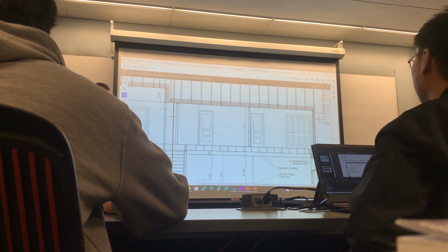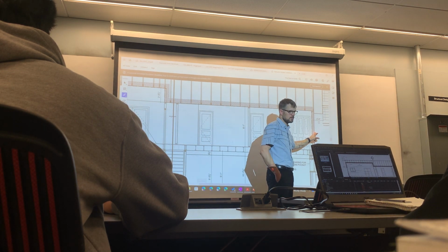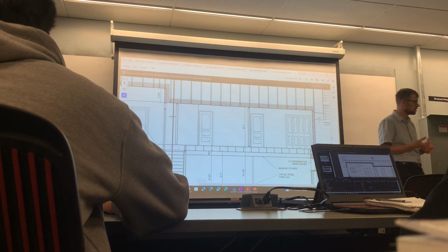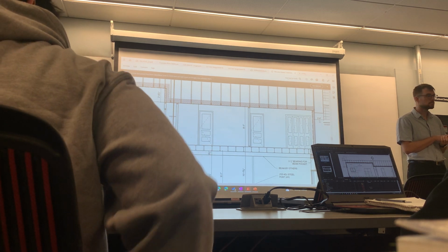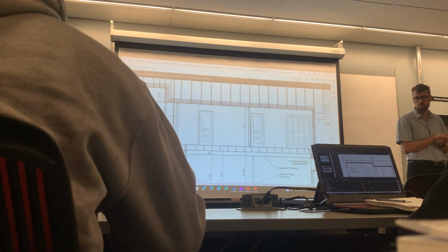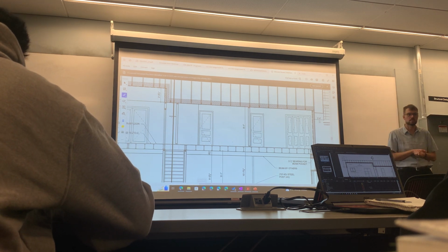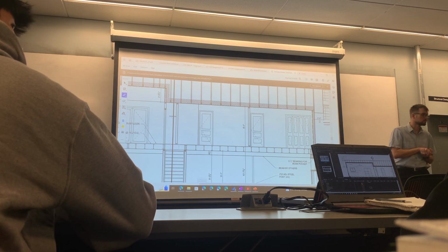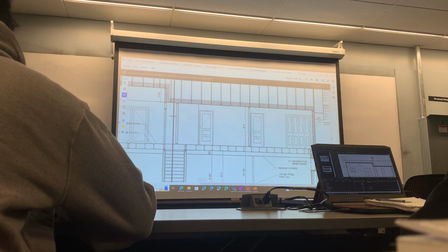What would the taller walls have a tendency to fail more than the shorter ones? We said buckling, deflection. Bearing? Bearing will be the same. A little bit more wall self-weight, but insignificant, especially since we're not considering it. Have you got them all? If you want, look back at your notes.